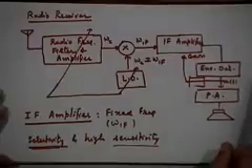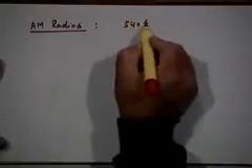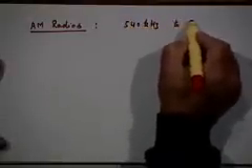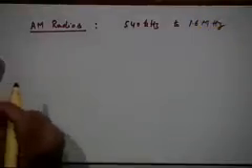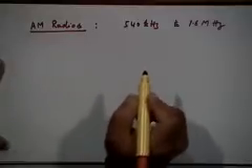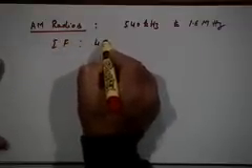To see things more specifically, let us take some figures. For typical radios that you use, let us talk about the AM radios. The typical AM band that you work with is 540 kilohertz to 1.6 megahertz, alright. And a typical convenient intermediate frequency to use is 455 kilohertz.